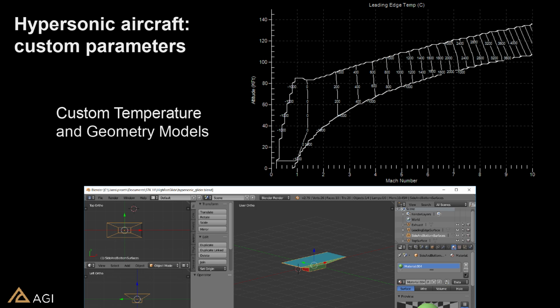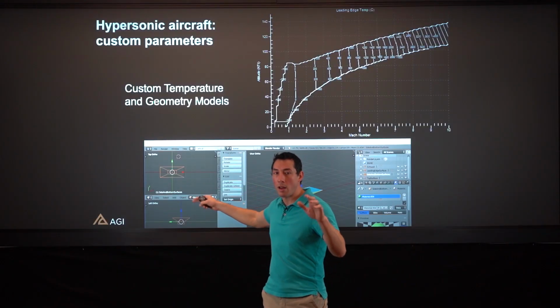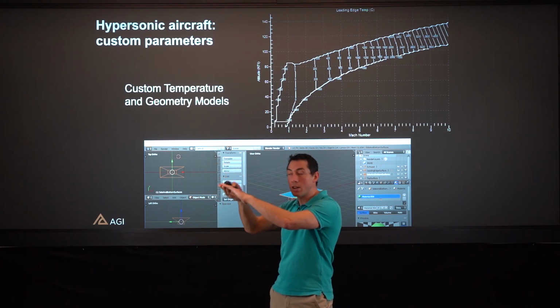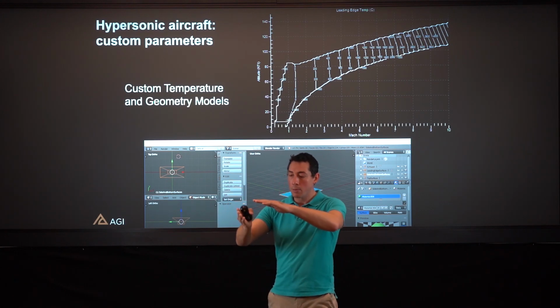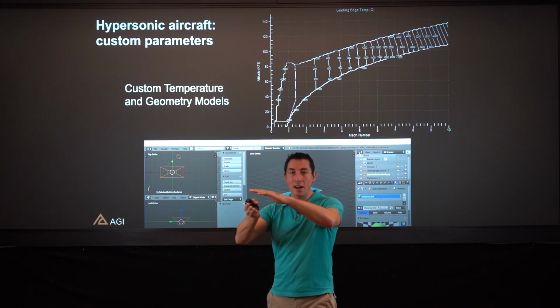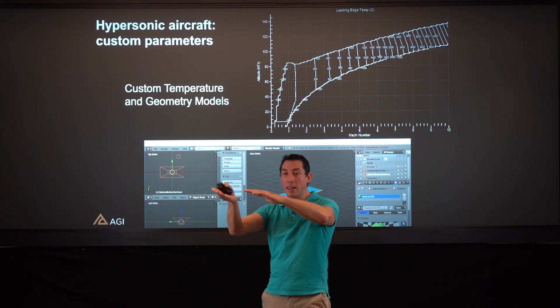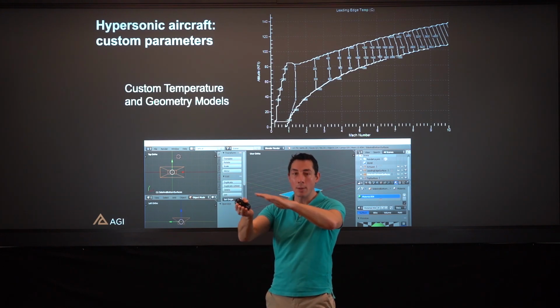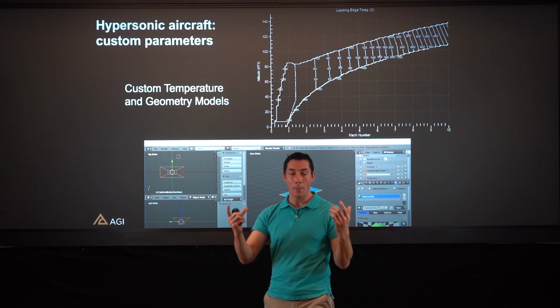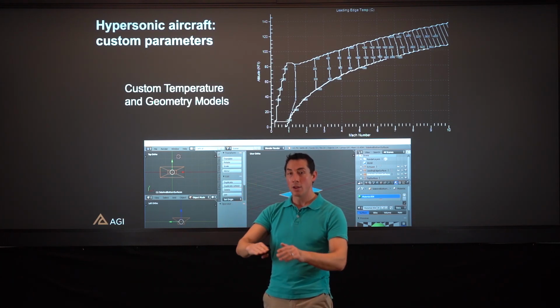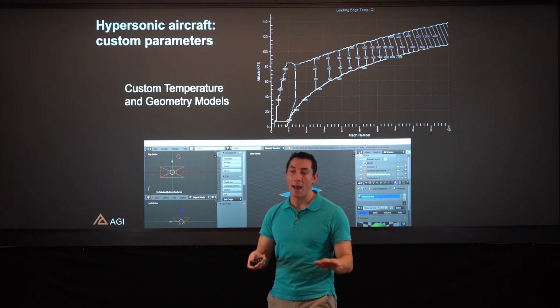That's amazingly hot. The problem is not the entire body of the aircraft is going to be that hot. If you look at the sample 3D model of a hypersonic primitive, the leading edge is going to be 1,600. The problem is the top surface, based on the way the airframe works and the fluid dynamics of this, is going to be almost ambient air temperature. It's directing all the airflow underneath that aircraft, and the top surface is unfortunately the very coolest part of the aircraft, which is what most of our overhead thermal imaging assets are meant to detect. So this is a really tough problem right off the bat.